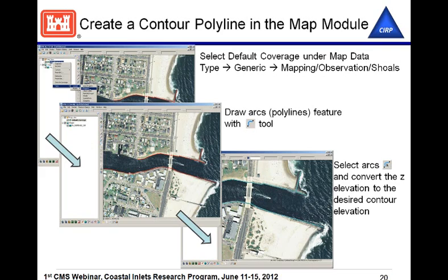And this slide just kind of shows how to bring in that data from the ArcGIS and convert it to an ARC within the SMS. I don't actually have the shapefile at this point. I just have the ending survey file as we want to bring in for SMS. So this would show how to do that if you had the shapefile from ArcGIS, which we don't.